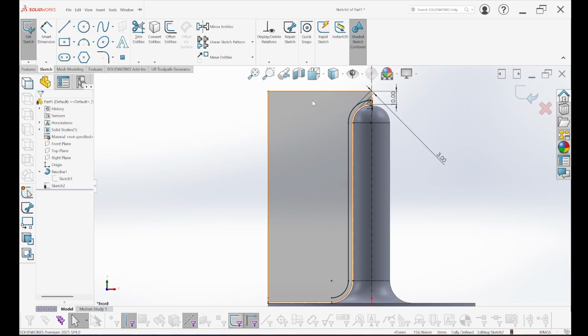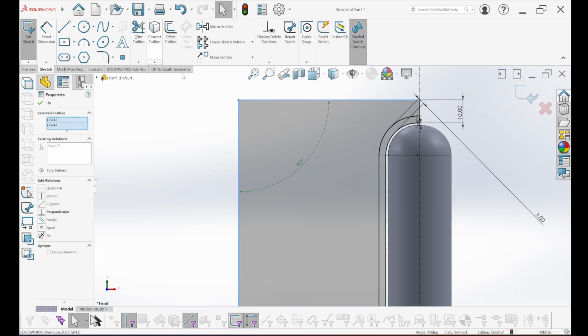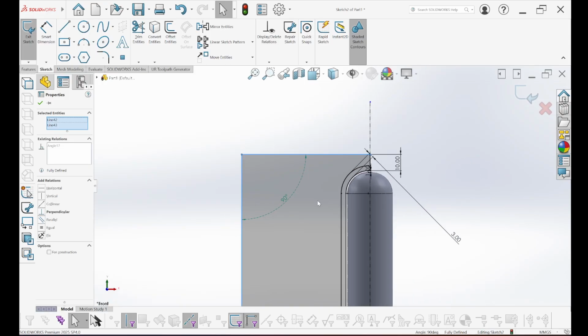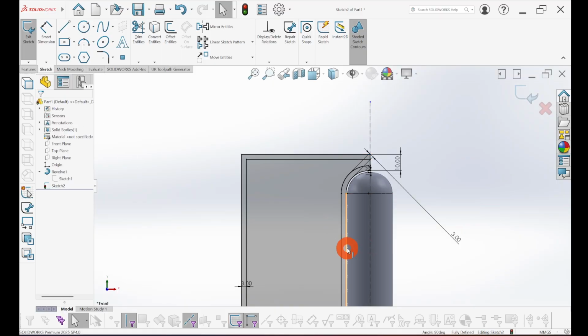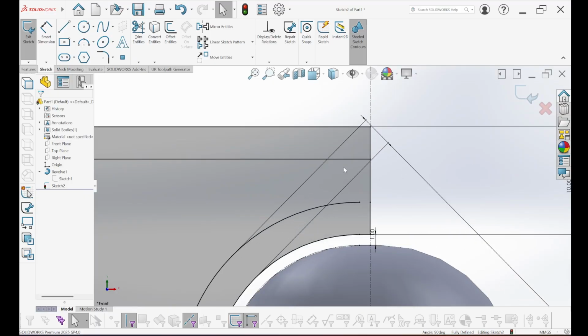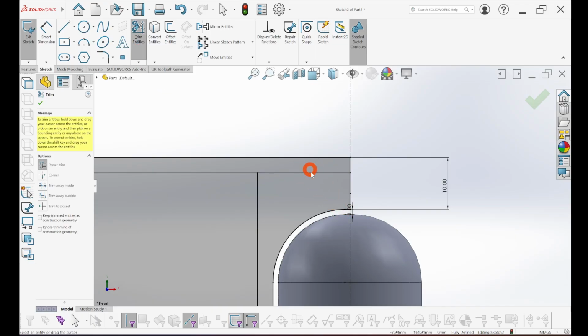So what I want to do here, I want to take that line and that line. And yes, let's do that. Offset 3 millimeter. In that case, I don't want selection change. I'm removing it. I don't want cap end. I just want the 2 lines. I can play with the reverse just to be sure that I'm duplicating in the correct direction, and save. Now that I have this, I can remove this one, delete. I'm gonna use extend entities until here, trim entities to clean.